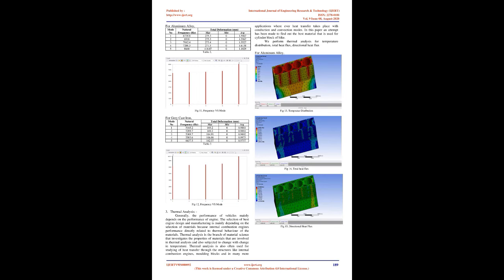Linear static analysis has three main assumptions. 1. Forces are linearly proportional to deformation. If you double the loads, the response, displacements, strains, and stresses, also double. Stress is proportional to strain. 2. When the loading is removed, the material must return to its original shape. No plastic deformation. 3. Boundary conditions do not vary during the application of loads. Time-varying loads, dynamic loads, vibrations, and temperature cannot be applied in linear static.